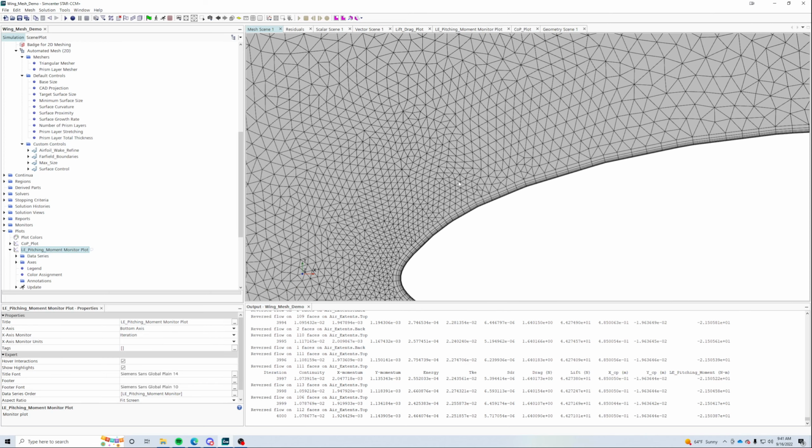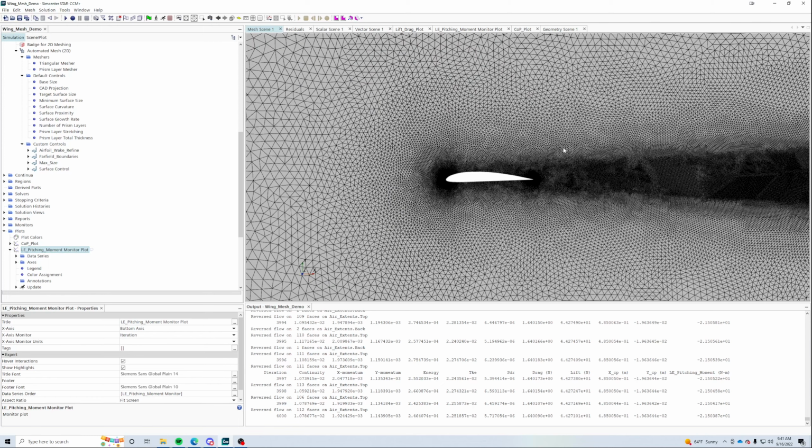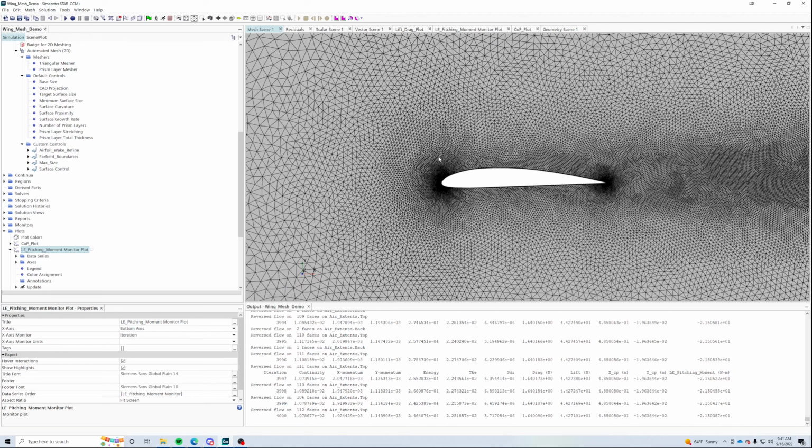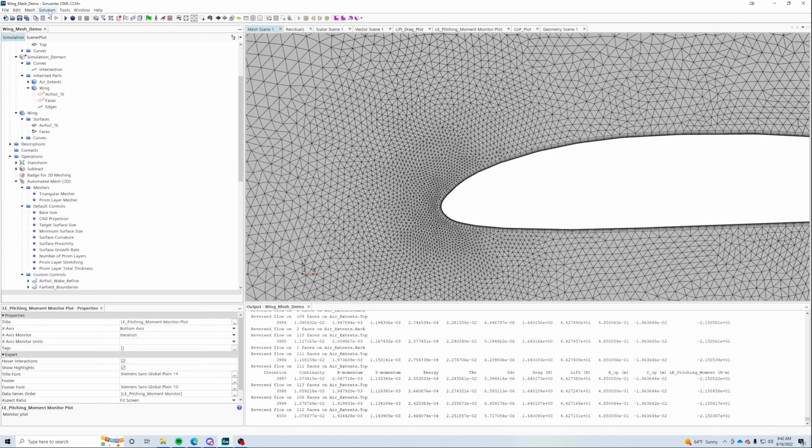Whereas polygons, you don't need as many of them, but they have more sides. So it has to do with the math of how you link these cells and the matrix math that results from them. In general, for 2D, polygonal is my go-to because it generally results in the highest quality, most robust meshes. It doesn't always, but it usually does in my experience. Quads don't really work all that well in 2D. Triangles work pretty well in 2D, but you need a lot of them. You really do need a lot of them.